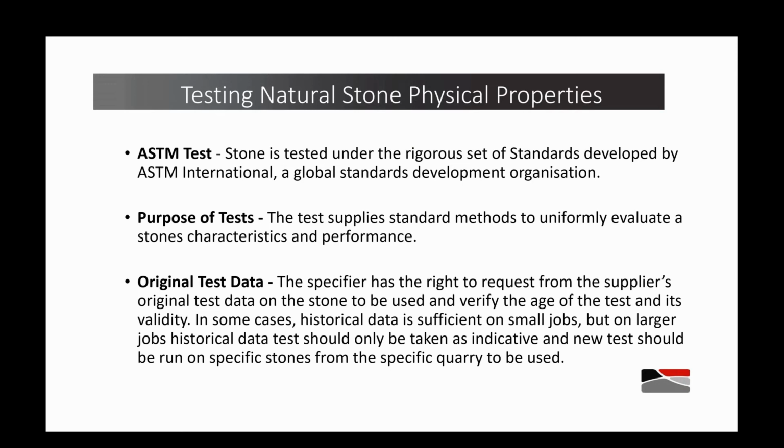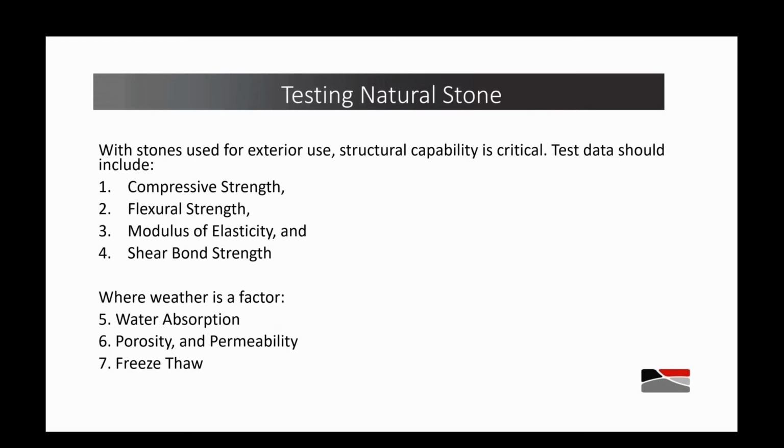Anything that will potentially affect the durability and the life of the stone, as well as the appearance. There are many other tests than these, but these are the core ones: compressive strength, flexural strength, the modulus of elasticity, and shear bond strength. The shear bond strength also speaks to mortar, but it's an important one.